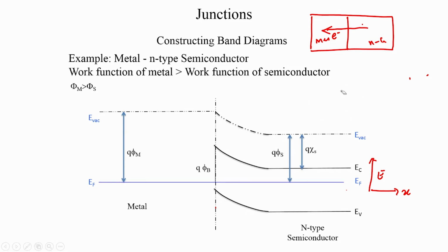And therefore, since this is the case, if I have an electron and a hole, the electrons will like to run down the hill when you see a bending, and the holes will like to run up the hill. So, this gives you a very intuitive feel for what the electrons and the holes would do. Now, since it is an n type semiconductor, there are not many holes, there are very few, and whatever majority electrons were there have all moved into the metal, and essentially any electron coming in here will try to run down the hill and away from the junction.